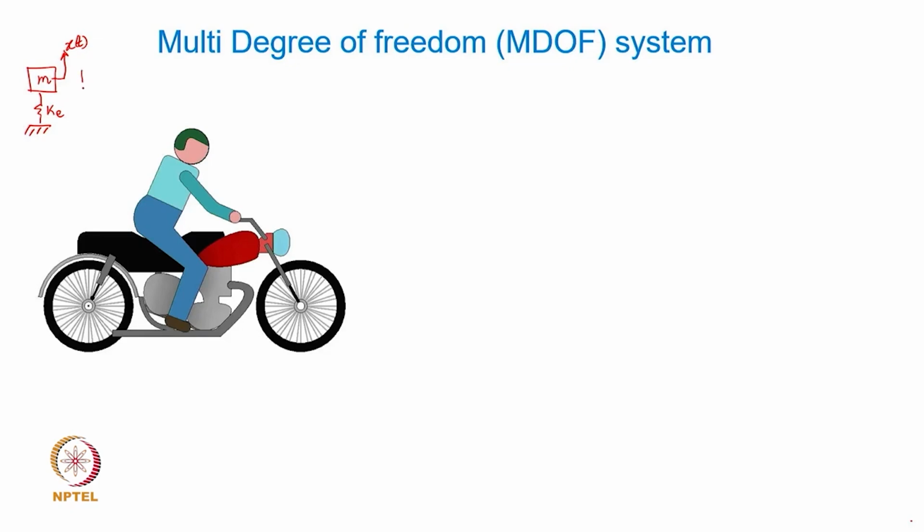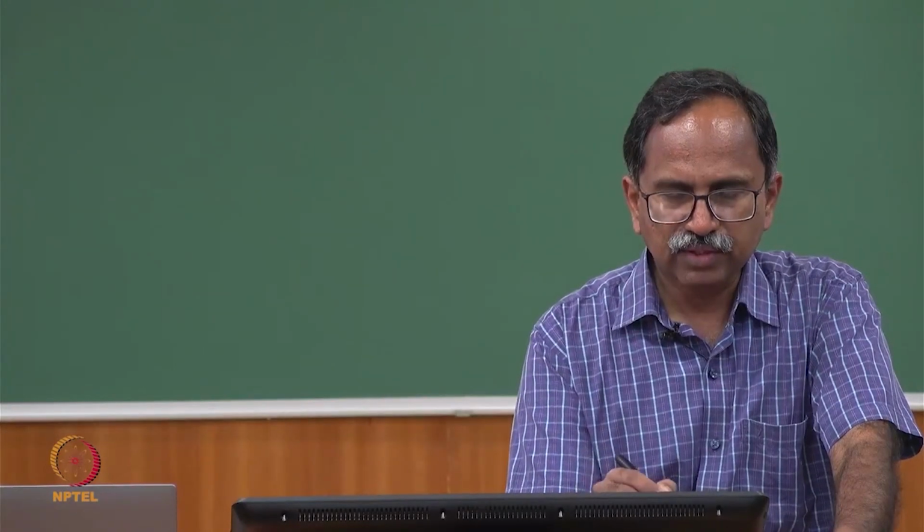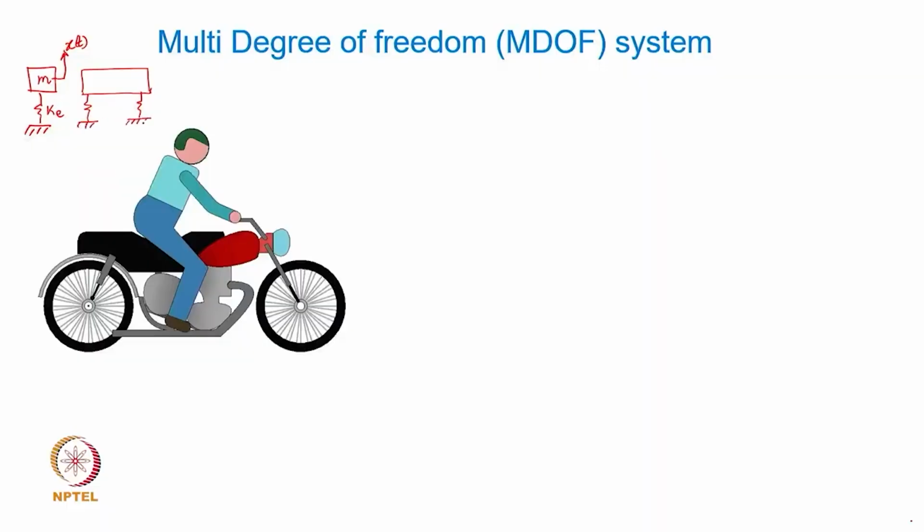Later on we discussed that for a car, an automotive which has maybe a different suspension characteristic, we also look at other degrees of freedom which could be important. So, this kind of a pitch motion, this kind of a bounce or a heave motion, we included. In that case an additional tilt degree of freedom, the theta, the angular motion theta, and the heave motion or a bounce motion like y. And later on in the previous topic of transmissibility, we looked at what things can change if we include another degree of freedom, that is a horizontal motion.